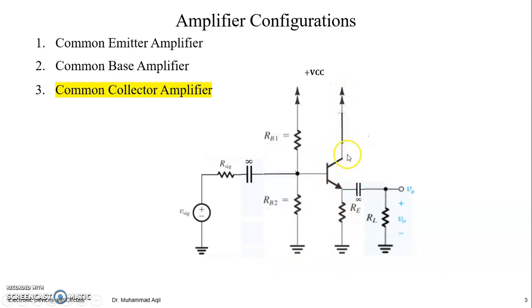since you have an NPN transistor, you have to have the collector more positive than the base to have reverse bias here, and forward bias here would be possible if the base is more positive, at least 0.5 to 0.7, then it will be forward biased. So forward, reverse, it will work in the active region, right?